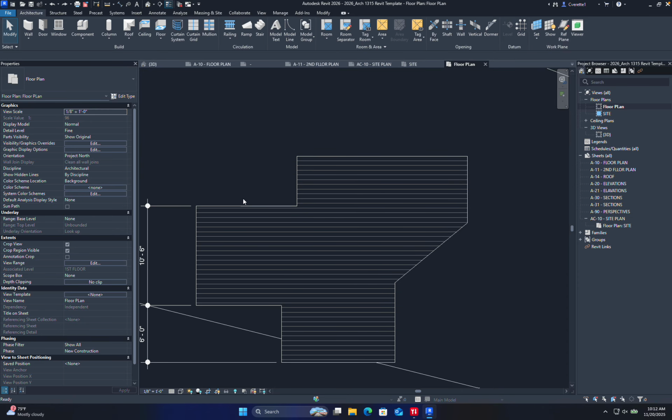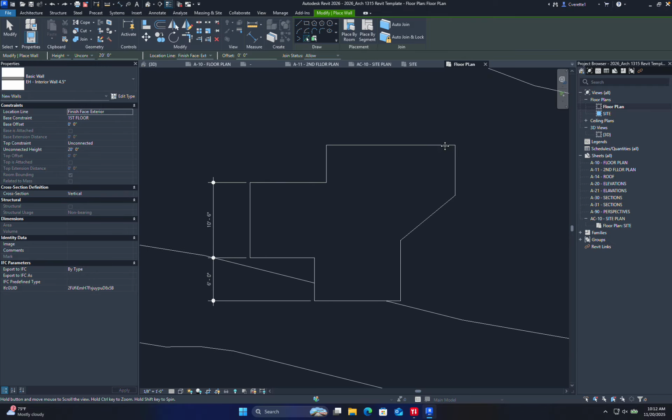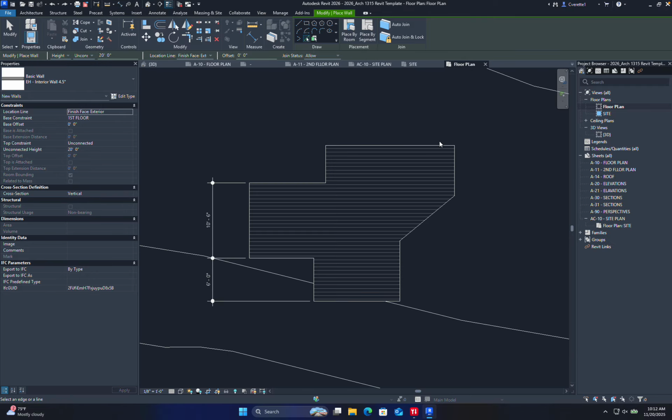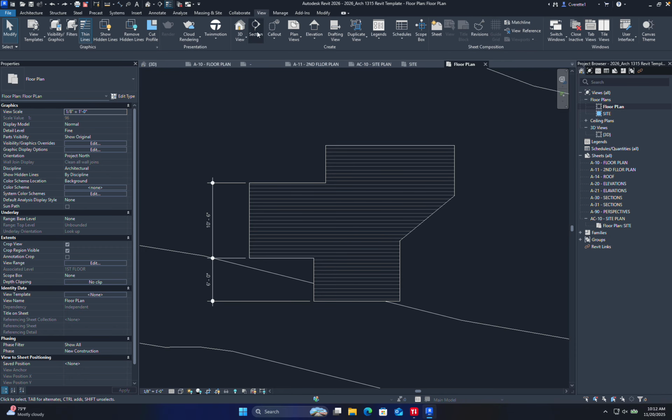Another way that we can make some walls is you'll see this pick line tool. That's one of my favorites. I pick this line and I can control some things at the top, for instance, how tall the wall is or what it's connected to. That actually brings up some good detail. I might actually want some of my elevations or a section so that I can start piecing this together myself. In fact, I'll go to view, and voila, right?